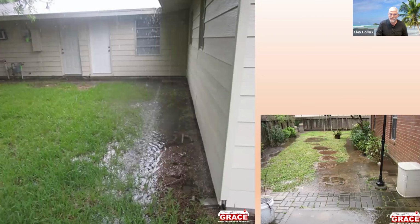No gutters. Gutters with a splash block would not have done much good for them, because the typical downspout and elbow and splash block would still have been underneath that roof. So they're still trapping it in that area. The only way to really successfully handle this would be gutters to underground drains, or that 5-foot downspout extension, which wouldn't happen.